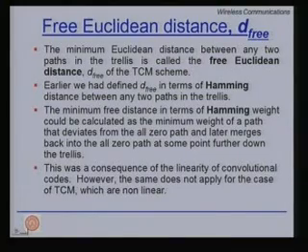But one word of caution: convolutional codes are generally linear by definition. The construction that we do uses linear adders and shift registers, so you end up making a linear code. On the other hand, the nonlinearity is introduced in the mapping process, because you are mapping the 3 bits, for example, to 8 PSK symbols.